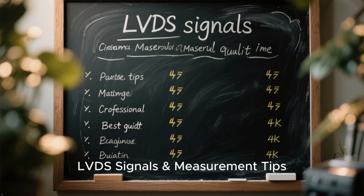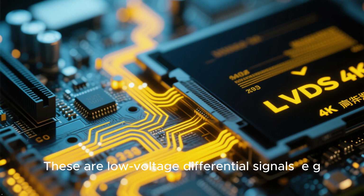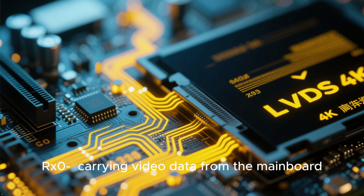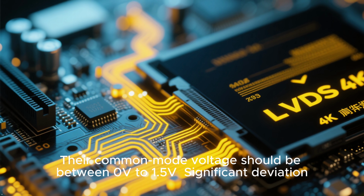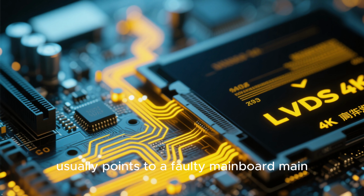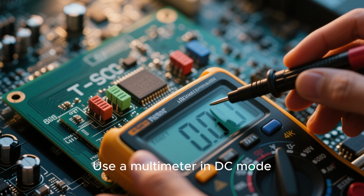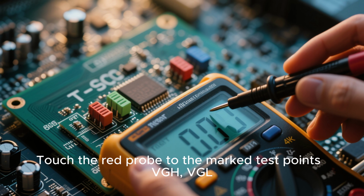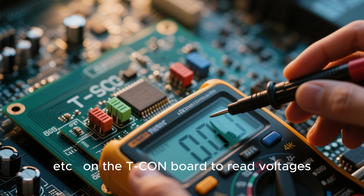Bonus information: LVDS signals and measurement tips. LVDS signals are low voltage differential signals, for example, RX0 plus, RX0 minus, carrying video data from the mainboard. Their common mode voltage should be between 0 volts to 1.5 volts. Significant deviation usually points to a faulty mainboard main IC. How to measure: use a multimeter in DC mode. Connect the black probe to a solid ground. Touch the red probe to the marked test points, VGH, VGL, etc., on the T-con board to read voltage.